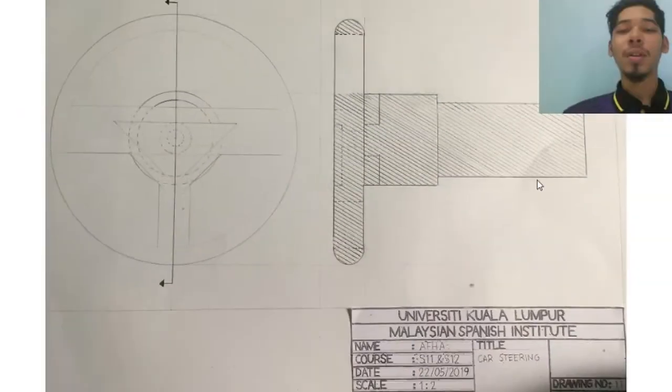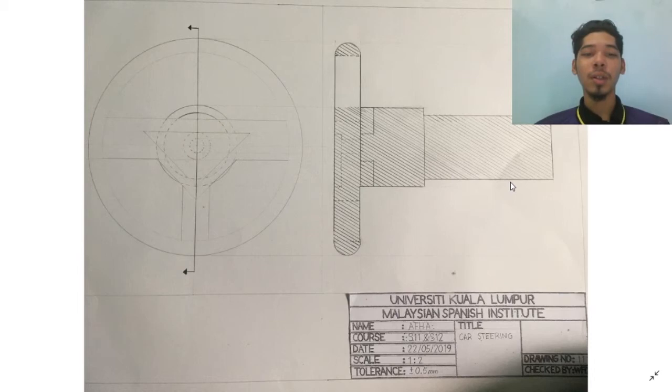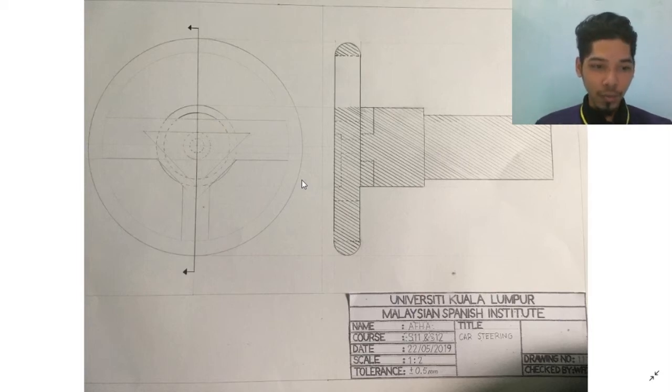Thank you. Now we will move on to the next section. This drawing that we can see is a section view. I will talk about the section view. The section view is a view used on a drawing to show an area or hidden part of an object by cutting away or removing some of that object. This drawing is very important to visualize what the part will look like after it is cut open.